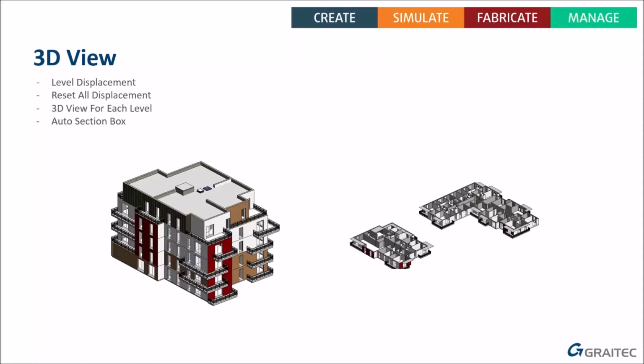You can then orientate it to a level. Then you've got to duplicate that view, right-click, orientate to a level, duplicate the view, right-click, orientate to a level. And we've got some really nice tools which will absolutely speed that process up very, very quickly.